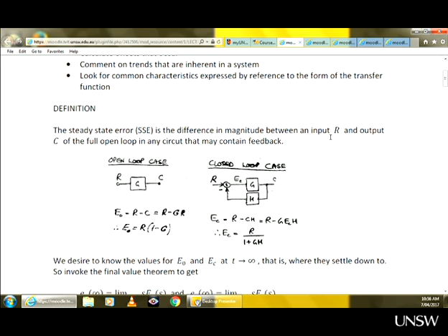Actually this is a good example because we have temperature sensors here, so it is a closed loop system. The system is giving us 25, but the sensor keeps checking that temperature and creating an error signal to reduce the temperature. But if the system is of such a type that it never gets the steady state error to 0, we need to know that.